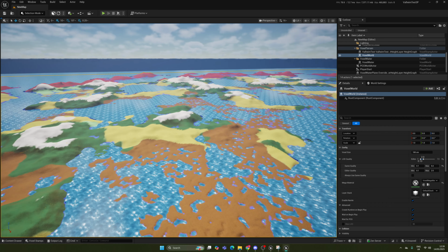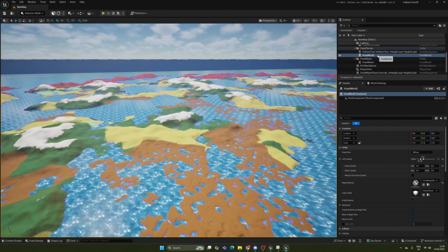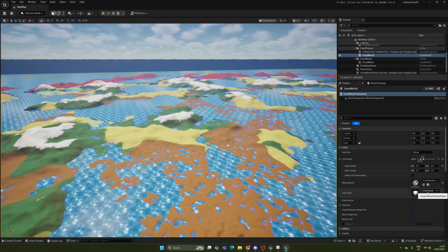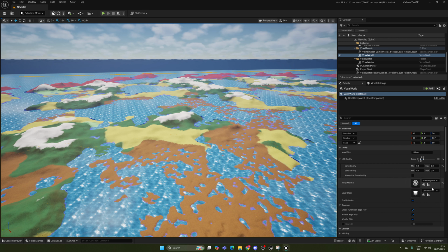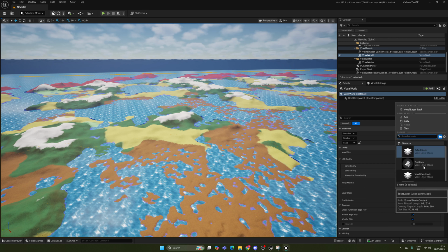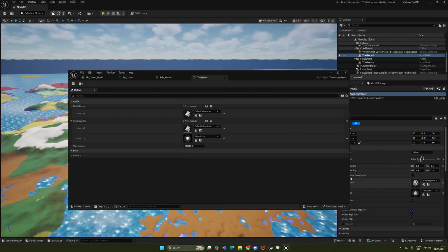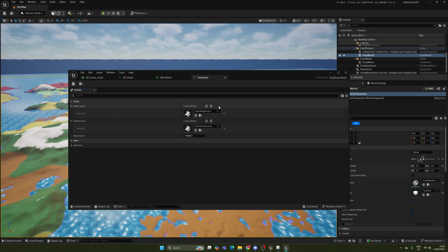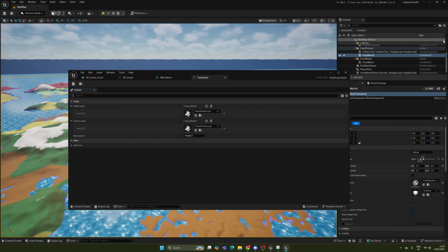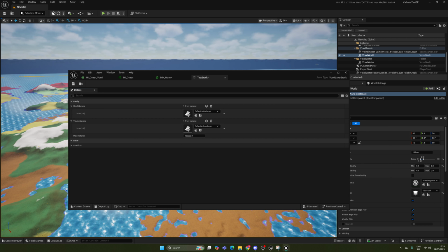Okay, now we are going to create splines. First of all, we're going to update our terrain stack, because I also need to add a spline layer to our terrain stack. So I'm actually going to move away from the default stack, and I'm going to use a test stack that I had set up previously. I'm going to keep the default layer because our graph is right into the default layer, but I'm going to add a new layer for spline terrain.